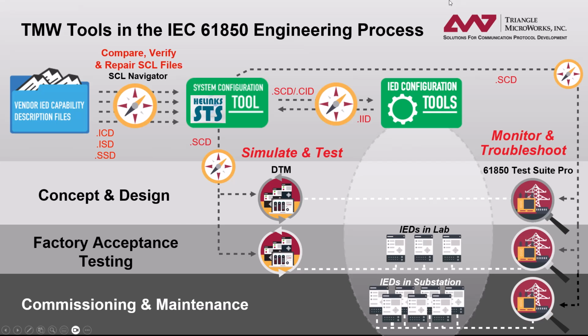During this phase, manual and automated tests can be created to ensure your configuration of your devices will behave properly. Next, during the factory acceptance testing, you can use that same simulation you created in the previous phase to test your physical devices as you get them. Each device can be inserted into the environment where the simulated counterpart could be disabled. This allows you to run those automated tests again with each device individually before integrating them into your physical system as a whole.